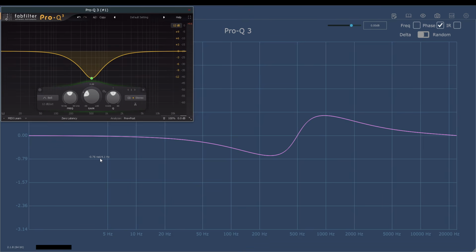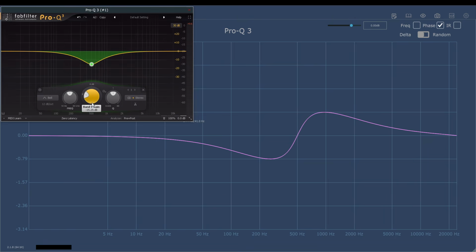Another thing to notice, this is quite a significant EQ cut, but the phase shift still doesn't get anywhere near wrapping around at 180 degrees like the all-pass filter did. Mixing this EQ'd signal with the dry signal isn't going to cause any drastic cancellation or weird coloration of the sound. In practice, it just slightly changes the width of the cut or boost you're applying.